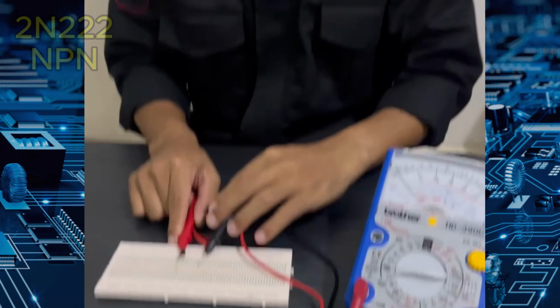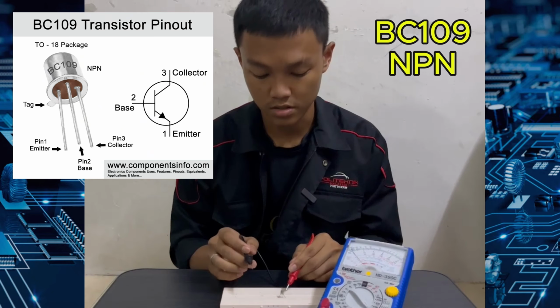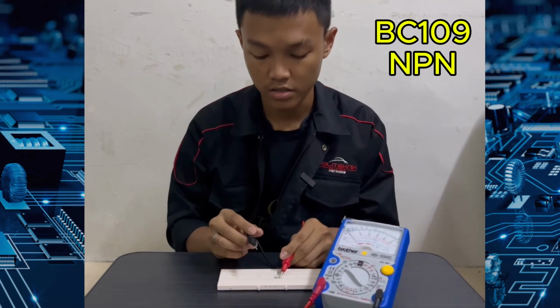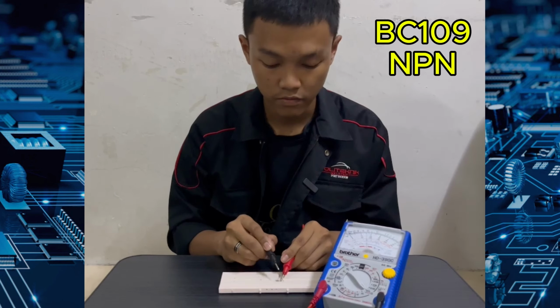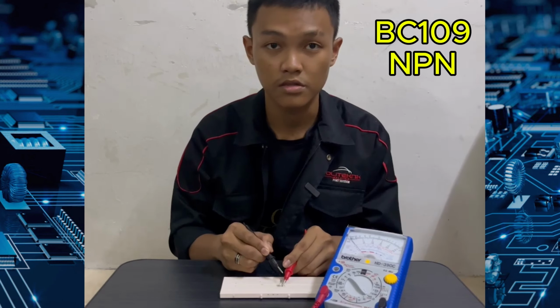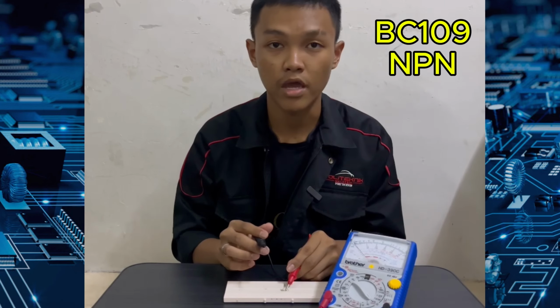That's all from me. So now I'm going to identify the BC109 transistor terminals. For the base, I assume the middle terminal is my base. I put the red probe here and the black probe to the other terminal. For the other terminal, it should have the same value. So this is my base. Since my base is on the red probe, my transistor is NPN.